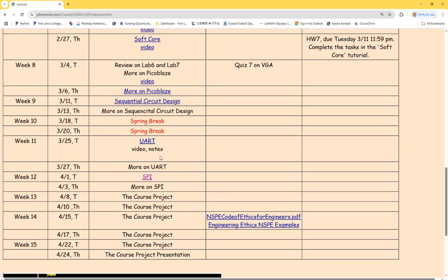If it's too fast with a long cable, the cable has parasitic capacitance. It's capacitors everywhere, even though you don't see it, but actually it's everywhere with the cable, with the rubber material, metal to metal. The rubber is a dielectric material, so it's forming caps along the line. So eventually, if you're running the signal really fast, it won't be able to charge and discharge efficiently to the little parasitic capacitance. Okay, so high speed won't be able to transmit through a long distance.